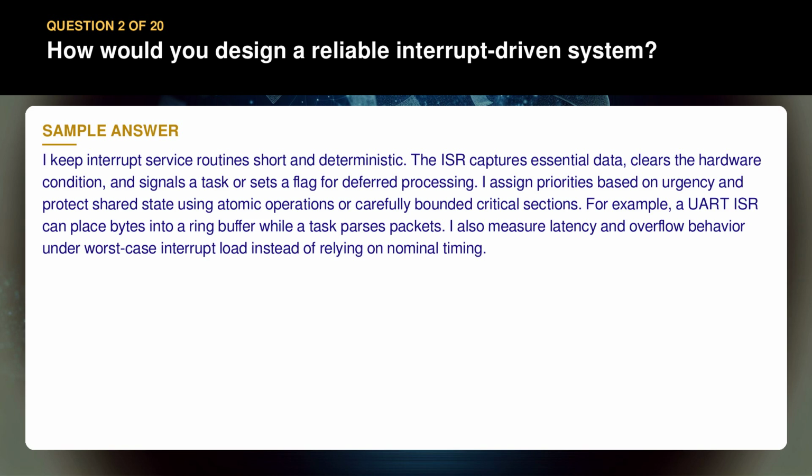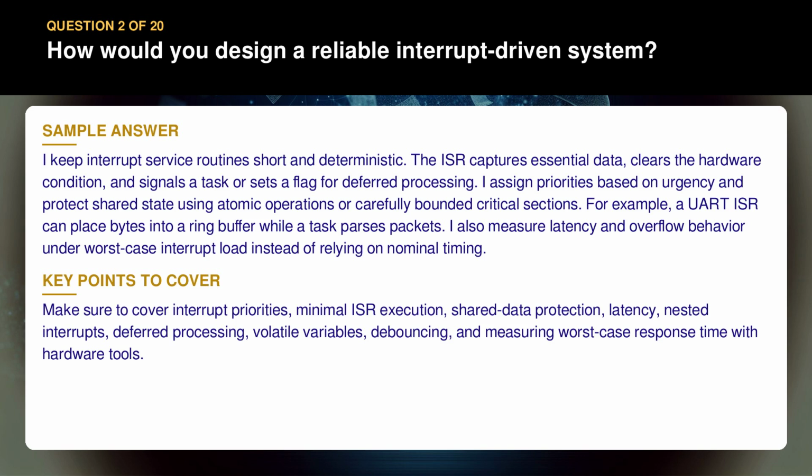I also measure latency and overflow behavior under worst-case interrupt load instead of relying on nominal timing. Make sure to cover interrupt priorities, minimal ISR execution, shared data protection, latency, nested interrupts, deferred processing, volatile variables, debouncing, and measuring worst-case response time with hardware tools.